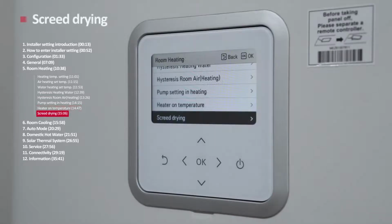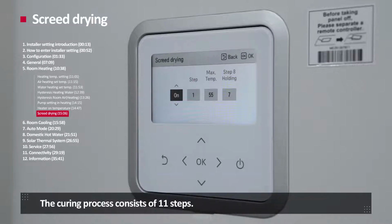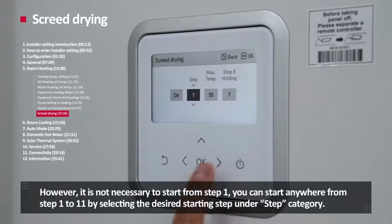Screed drying. Screed dry setting is to help with curing the new cement floor after construction by using floor heating for a certain period of time. The curing process consists of 11 steps. However, it is not necessary to start from step 1. You can start anywhere from step 1 to 11 by selecting the desired starting step under step category.